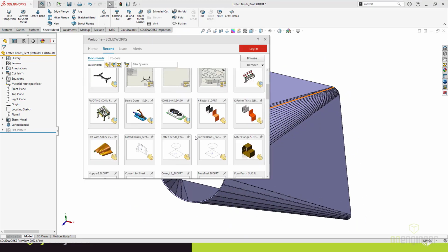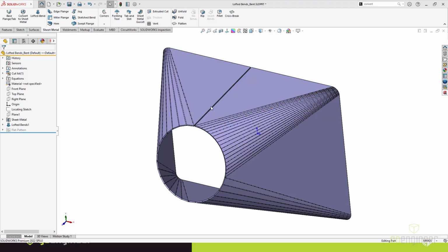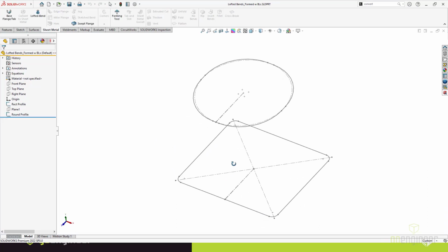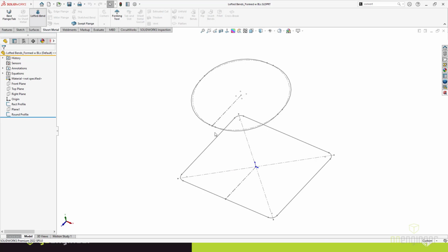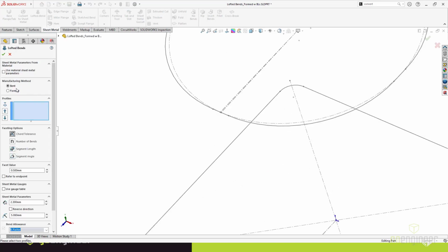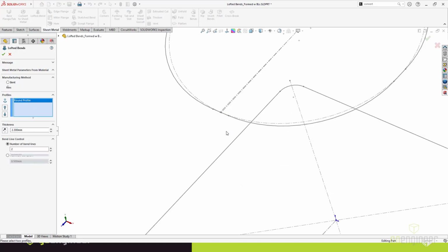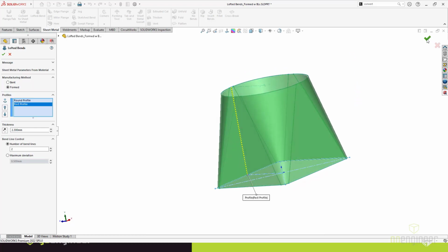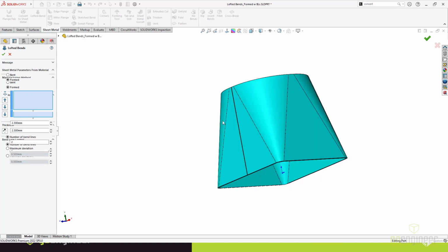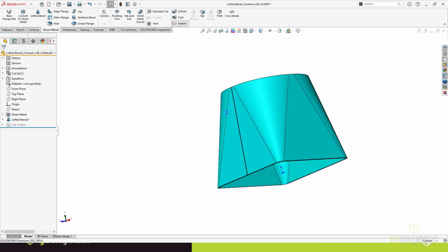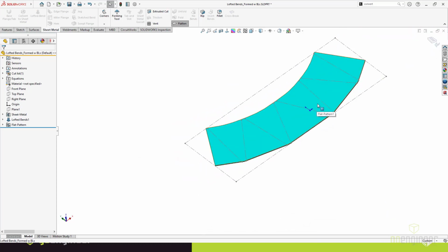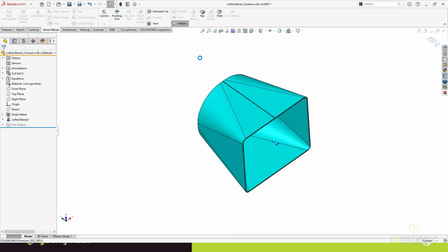The opposite part of that, again, is the formed feature. So now we're talking about something where we've prepped it a little bit for something like this, but not sharp corners. We've actually prepped it with radii features. So same operation. Let's go formed on this one. And with any loft, we're just picking these lofts roughly where they're going to bend. So now you don't see those individual bends, right? And what you're basically getting here is a smooth-ish part, I guess. We did put arcs in there, so you're kind of seeing the facial segments, but if we don't put those arcs in there, then you're not going to see each of those features.